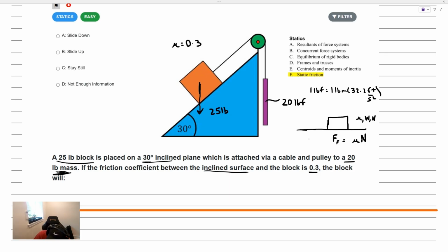If the box is sitting on the table and the friction force was equal to mu times n, we'd expect this box to go flying left or right? But that's not what it's doing. This friction force, which is the product of mu times n, is the maximum possible friction force. Friction is self-adjusting. So if I apply 1 pound here, that means that the friction force will oppose that motion. It will oppose that force with a magnitude of 1 pound. If I apply 2 pounds, it'll oppose 2 pounds.